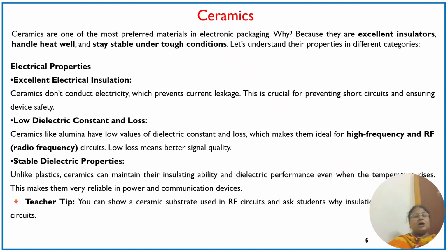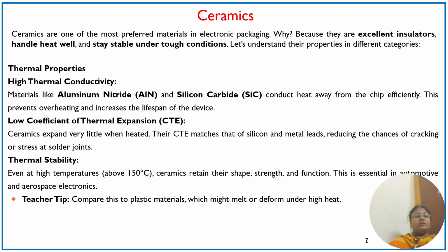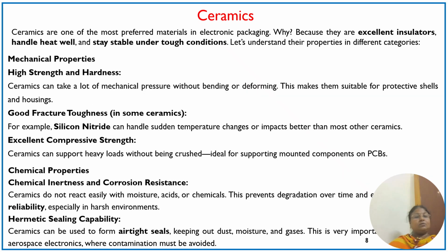So these are the electrical properties, and how it is achieved in terms of heat, stability, and tough conditions also. Here, different types of designs you can make, and thermal properties are very high, with thermal conductivity, low coefficient of thermal expansion and thermal stability. Above 150 degrees Celsius also, it's going to retain its shape, strength, and function. Hence, obviously, ceramic is used.